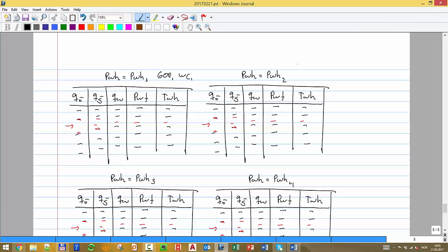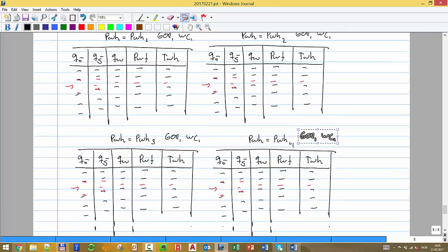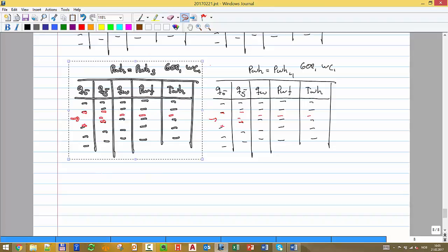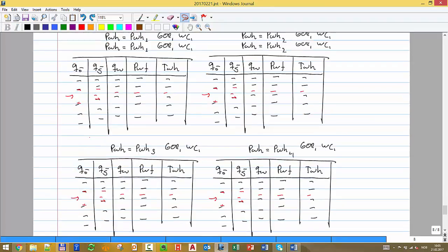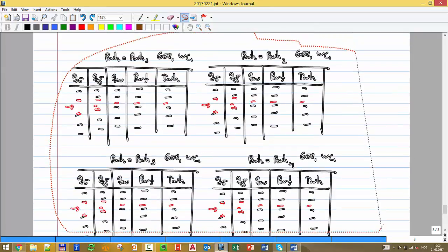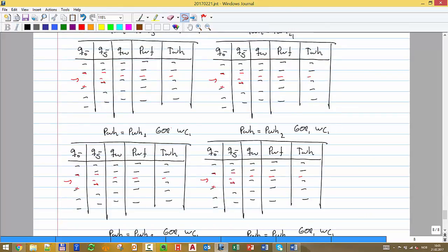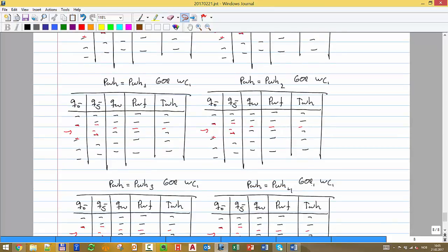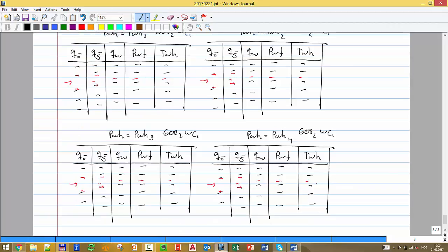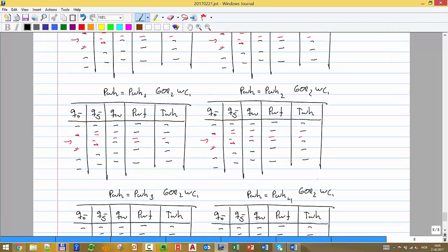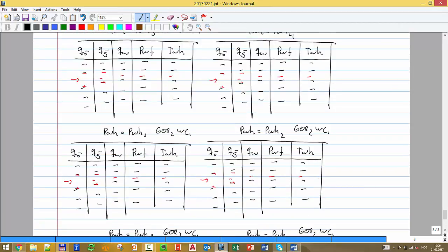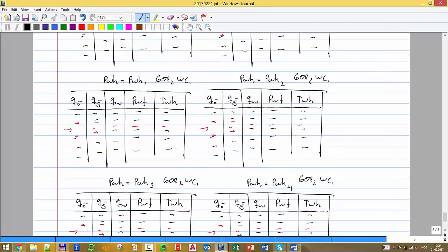Then I repeat the same thing. So that will be for a fixed GOR and a water cut. Then I repeat now with another, the same for the same wellhead pressures, but now with another GOR, but the same water cut, for example, with GOR 2, GOR 3, water cut 1, water cut 2, water cut 3, and if you see, in this case we're changing only 3 values, and already the amount of tables that we got is huge. So that's usually what we do with tubing tables.